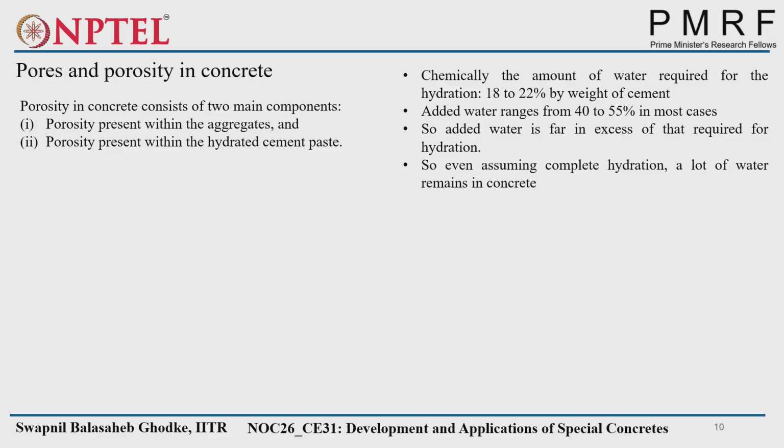Obviously it will be evaporated, because we will not continuously keep anything in the curing condition. After some time we have to remove even the cube, and even a slab will not be cured for its whole life, right? So after some time that water will evaporate. What will happen? That will leave some empty space in the concrete matrix, and that empty space acts as pores. That's why this extra water is dangerous actually.